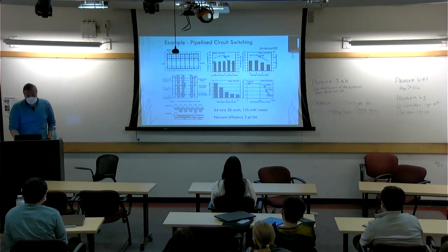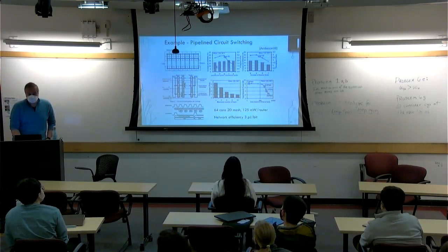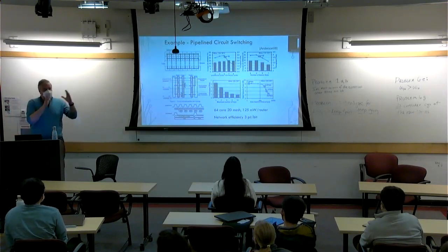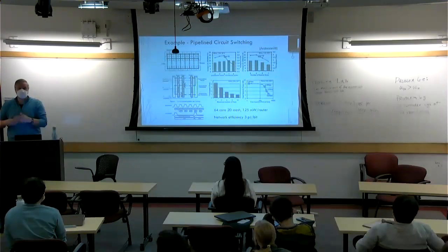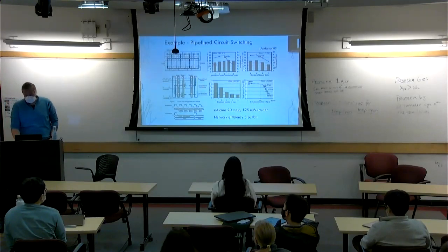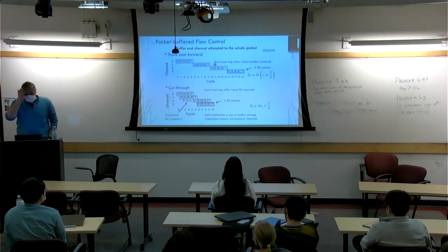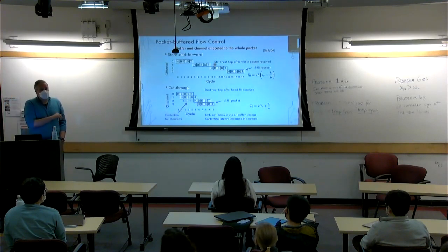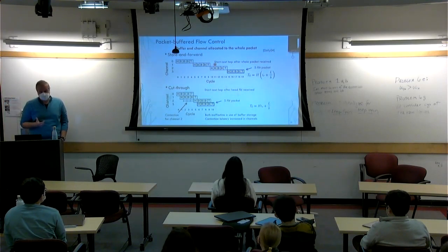And then they're playing with kind of the trade-off of packet cycles to circuit cycles. Again, you see that as your circuit clock cycle, meaning like how long is your message, right? If that reduces, your throughput also reduces because the overhead proportional to payload you're sending is smaller, right? So things like that. And then you have this other extreme, which is packet buffered flow control, right?